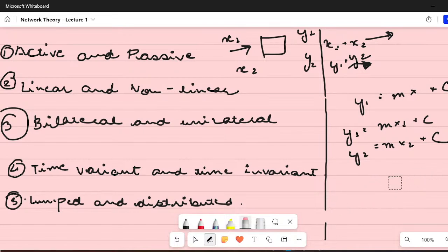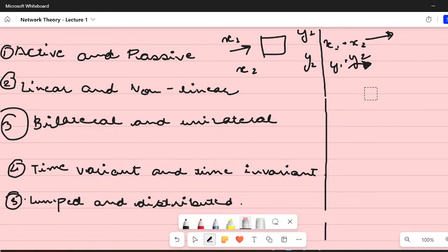It behaves as an open circuit. So when the direction of current changes, or when the applied voltage changes, the impedance offered, or the nature of the network, changes, and such a network would not be bilateral. It is a unilateral network.